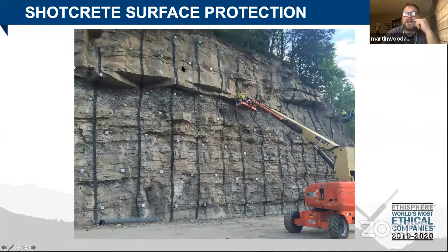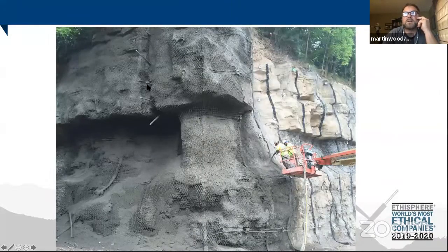The biggest thing with shotcrete is hydrostatic forces. So in this particular case, we're laying these vertical drain strips. We also employed horizontal drains in here. We do have vertical and horizontal whalers for integrity of the shotcrete, along with the anchors. And you start to look at, here's some of the horizontal drains and us shooting the shotcrete.